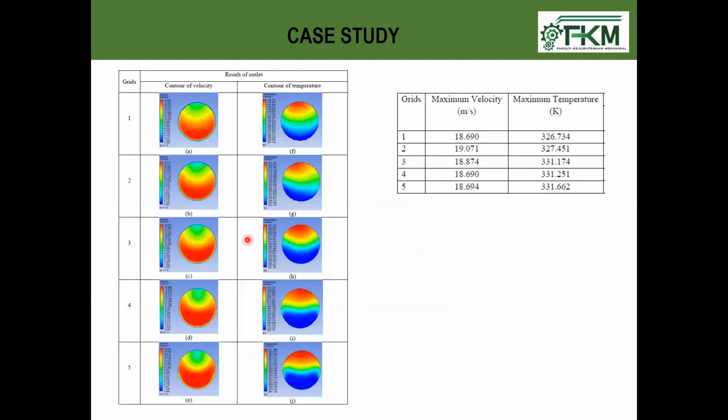So the result here is, we can see that between grid number 1 and grid number 2, it is almost the same. But when it jumps to grid number 3, you see that the green color becomes like this, compared to here it is much more diffuse, and this one becomes much more symmetrical. And when you try grid number 4, which is much higher, the green temperature region bulges downward a bit. There is a recirculation here, recirculation. And it is the same with grid number 5.